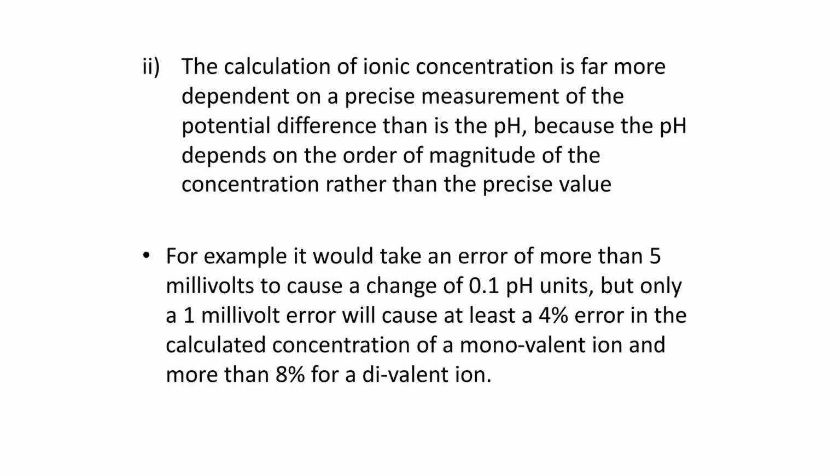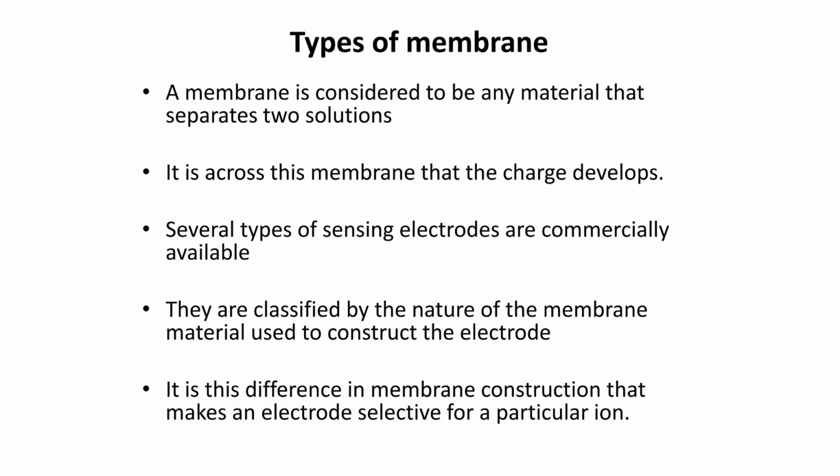When we immerse the electrode into the liquid test sample, the external hydrogen ions will spontaneously diffuse through the glass membrane, and this migration continues until a state of thermodynamic equilibrium is reached between the external and the internal ionic concentration. As a result, a localized charge builds up inside the membrane wall, producing a charge which is directly proportional to the total number of hydrogen ions.